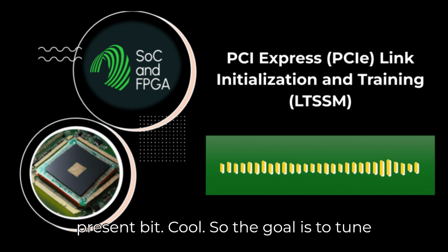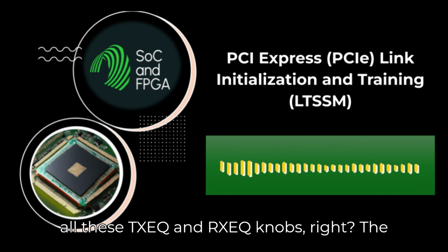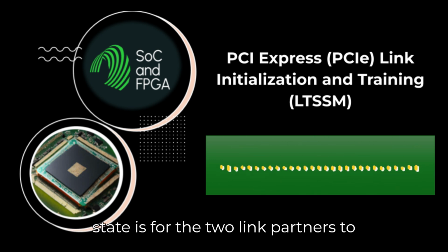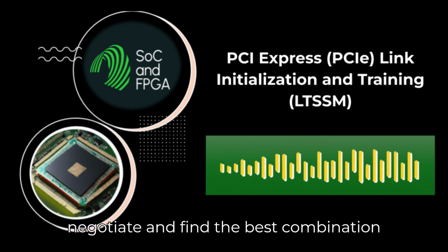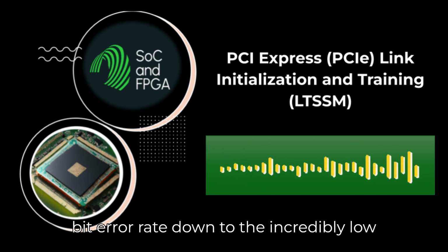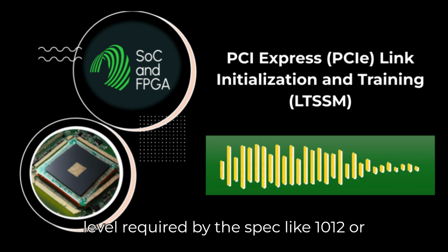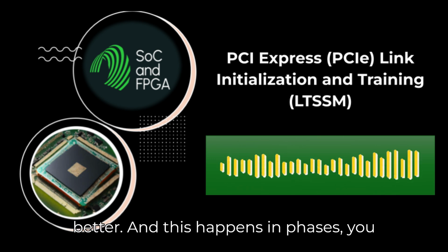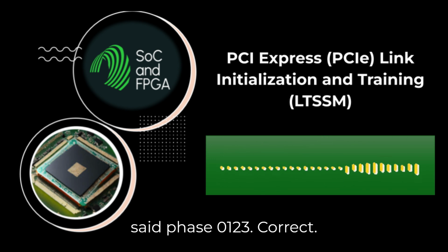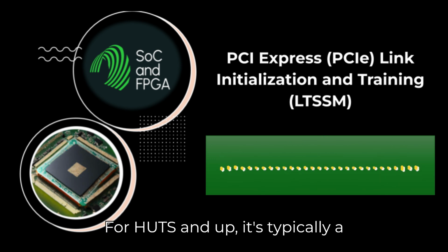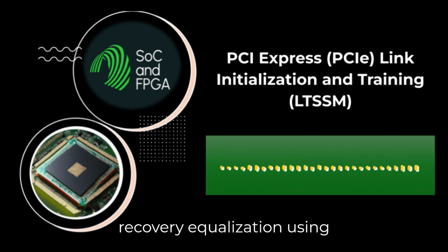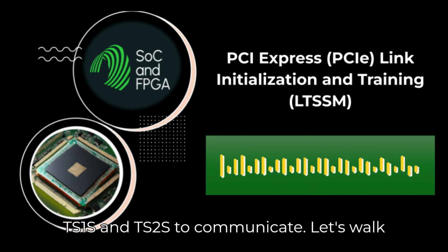Cool. So the goal is to tune all these TxEQ and RxEQ knobs. Right. The whole point of the recovery equalization state is for the two link partners to negotiate and find the best combination of TxEQ and RxEQ settings to get that bit error rate down to the incredibly low level required by the spec, like 10^-12 or better. And this happens in phases, you said. Phase 0, 1, 2, 3. Correct. For 8 GT/s and up, it's typically a structured multi-phase process within recovery equalization, using TS1s and TS2s to communicate.